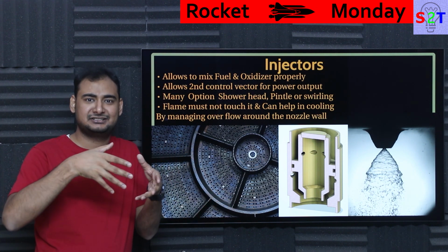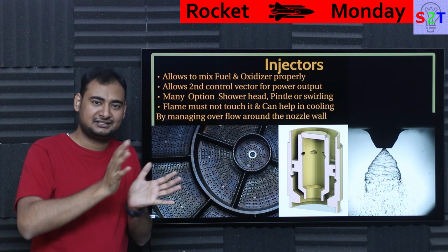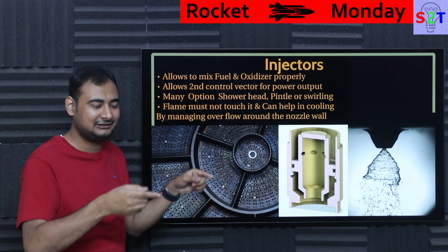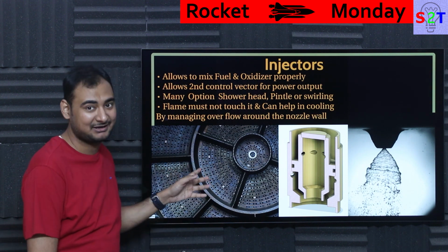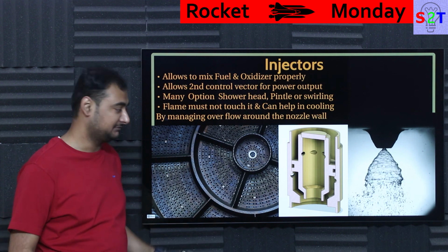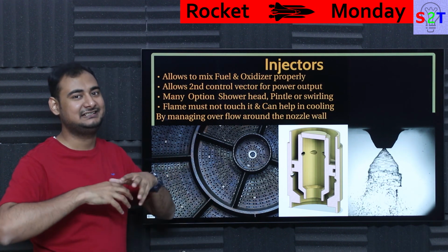Again, that's how a jet engine is also cooled. You have a jet engine and it's cooled by 700 degrees Celsius air. Yeah, 700 degrees Celsius is cool if your hot side is 1500 degrees Celsius. The same happens here. So you can design it this way, and this defines your specific impulse and everything, because this is the part where chemical energy is being liberated.